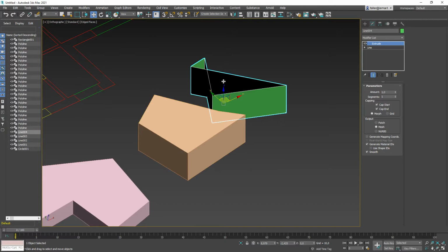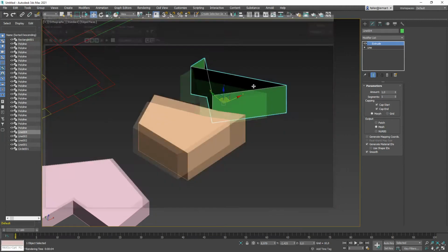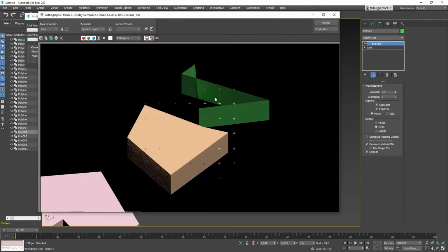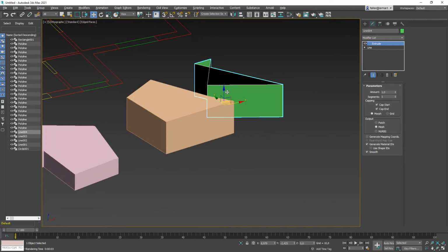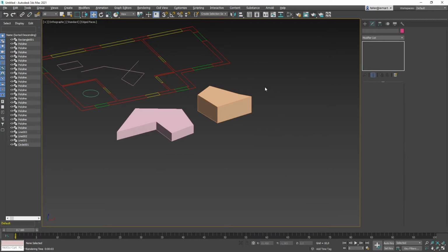Black means I see the back side of the face, and when you render it, the back side of faces usually doesn't render. Oh, it's hard to tell now. In this case, Arnold also renders them, but not as a solid object. So I rotate it slightly, and you can see through here because it's just a little wall. Good. That's something you want to avoid, so simply don't create self-intersecting polylines.